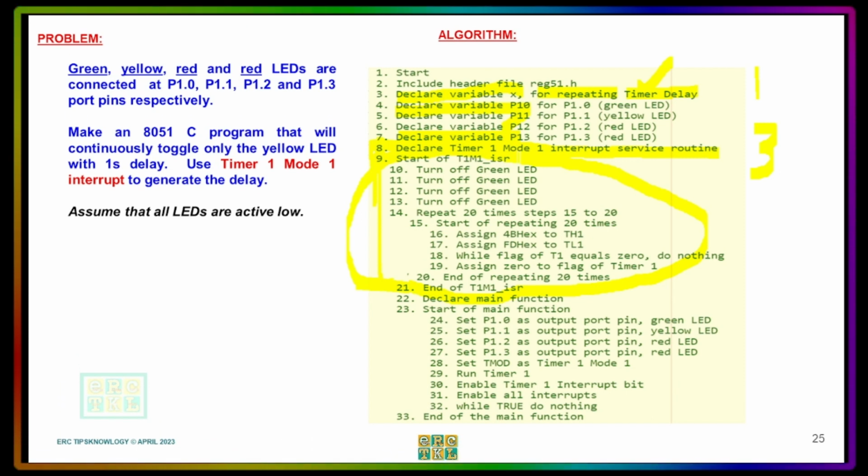It is when a device is requesting the service of the microcontroller, then the microcontroller will stop whatever it is doing and do the service for the interrupt. To do that, the interrupt must be provided with a task, and this task is inside a subroutine or a function. That's why we call it an interrupt service routine. To make it easy, we call this routine whenever there's an interrupt.